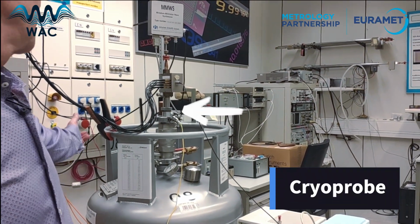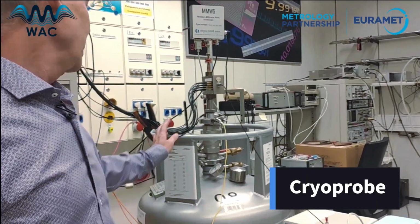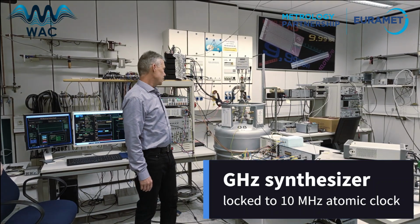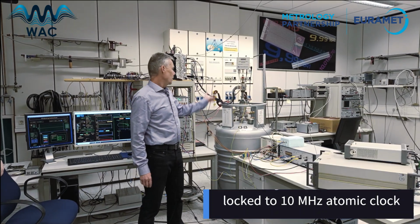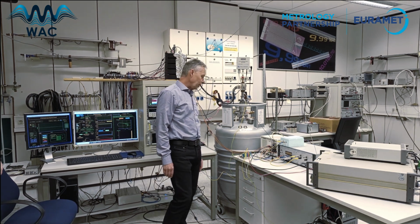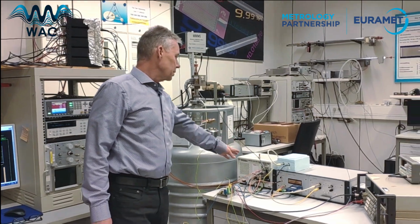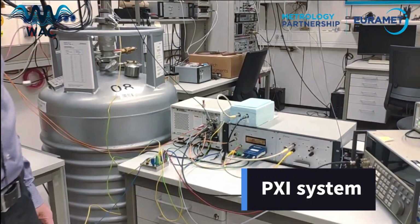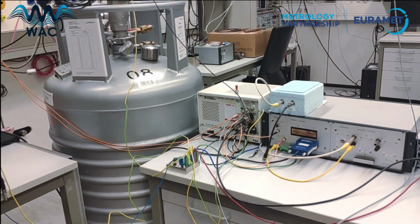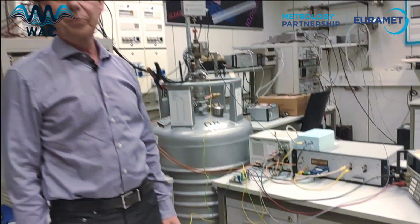All the segments of the cryoprobe are biased by this fast bias source, and we are using the 70 GHz synthesizer, which is locked to our 10 MHz atomic clock to provide the microwave frequencies. Then the output is going here to this PXI system, and now I will show you how we usually start with this.